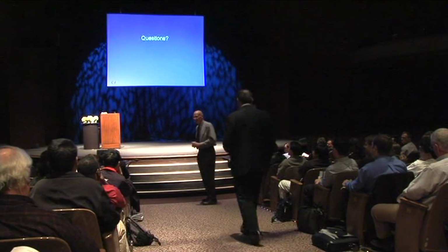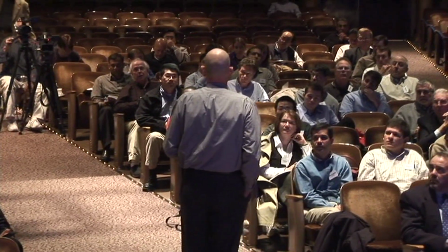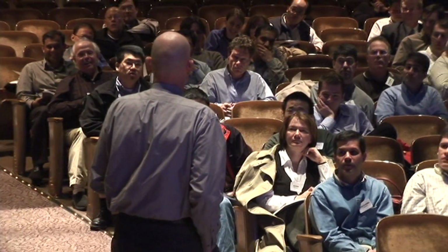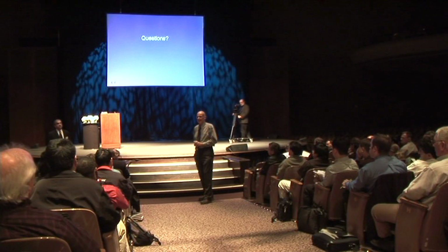Okay. Yeah, Dr. Powell. And how to consider the buckle in a column? You mean an actual column or a brace? It's a typical column in a moment-resisting frame. Yeah. Well, they don't buckle. I don't think so. The frame as a whole can buckle. It forms plastic hinges and forms a mechanism, and the p-delta effect can cause the frame as a whole to buckle. But I think you'd be pretty hard-pressed to find a column in a moment-resisting frame where the column actually buckles as a pin-ended column.